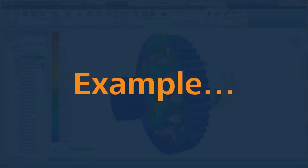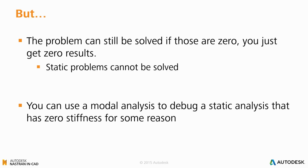Okay, so let's have a quick look at some further info. What happens if we solve this? Well, if you do solve it, it still will solve by running the modal analysis, and you'll find that the results will come back as 0 as well. Whereas static problems can't be solved using this same technique. And that's part of the advantage of using a modal analysis, we can actually use it to debug some of our static analysis studies and understand some of the reasons behind potentially what's going wrong with them.